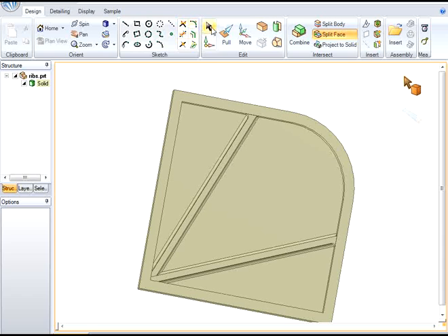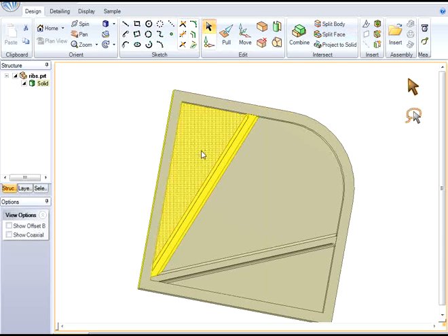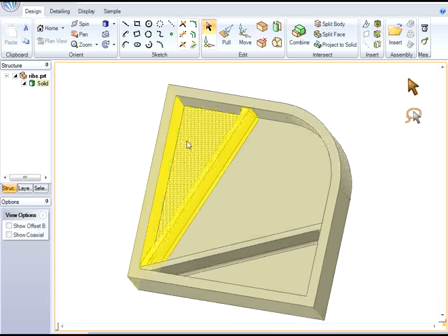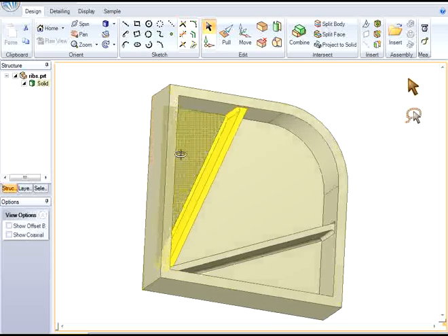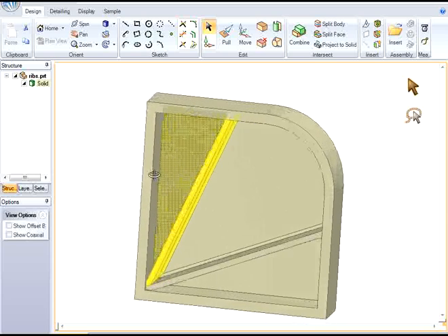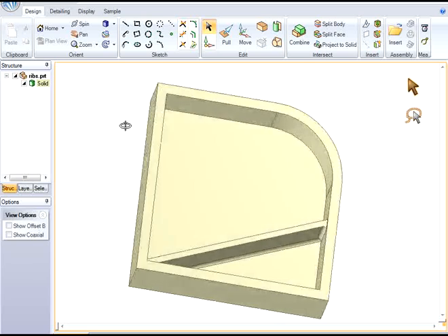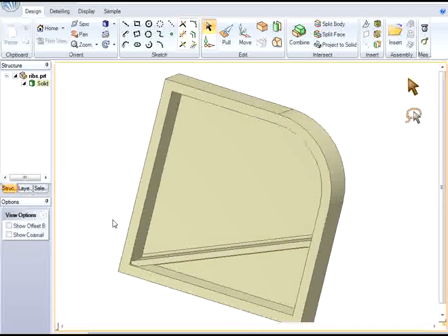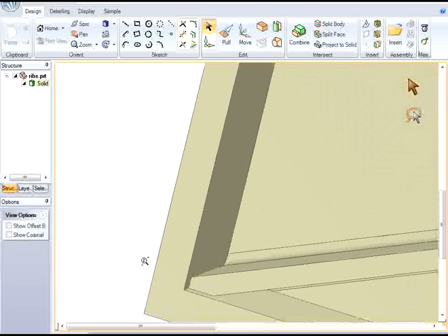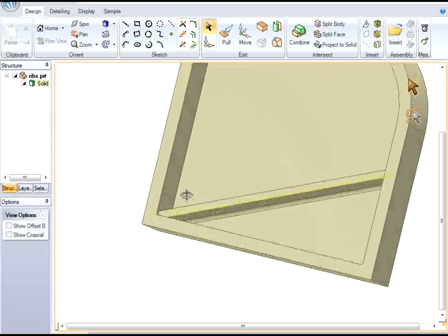Now let's just go ahead and choose. We'll select that top rib, and I've got a couple extra surfaces I don't need, so we'll control select to turn those off. And now we just have selected in yellow the rib and the rounds. And again, we can use the fill command, and that completely gets rid of that top rib. So that's the first step done. Now the second step is that we need to modify the existing rib that's left to move it up to a 45-degree angle.